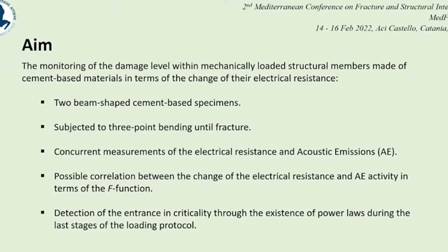In total, I will present you two beam-shaped specimens, which were subjected to three-point bending at deep fracture, and where we had concurrent measurements with electrical resistance and acoustic emissions. We will also investigate the possible correlation between the change of the electrical resistance and the acoustic activity expressed in terms of the F function. And furthermore, we will try to detect the entrance in criticality for the existence of power law during the last stages of the loading protocols.